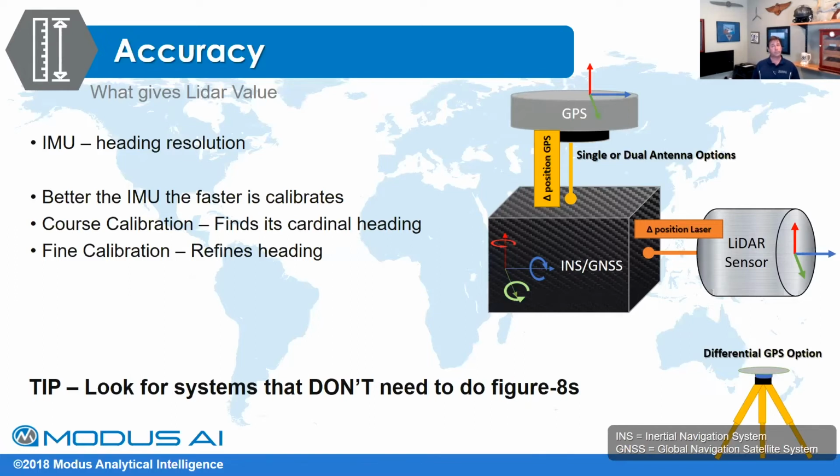So what I typically see is, someone will buy a brand new unit and they'll fly it by hand, and they won't really have good heading control, and they wonder why they're spraying the ground. They're seeing these little ripples in their data sets, and it all has to do largely with the IMU not being able to catch up with the heading hold equations when they're figuring out the inertial drifts that they have. Pitch is okay, altitude change is okay, but heading hold seems to be the big thing that you need to look for.